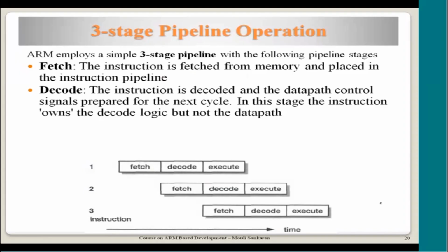Now decode is understanding the instruction based on the format of the instruction. I told you about the 3 parameter or 3 operand format, and then there is a functional code which also tells about what operation the particular instruction is expecting from the processor to be performed. So that information is decoded. Now why do we decode the instruction? Because only the instruction has the information about what the operands are, which registers are the operands, which register is the destination register, and what the operation is. All the information is available when the particular instruction is decoded,